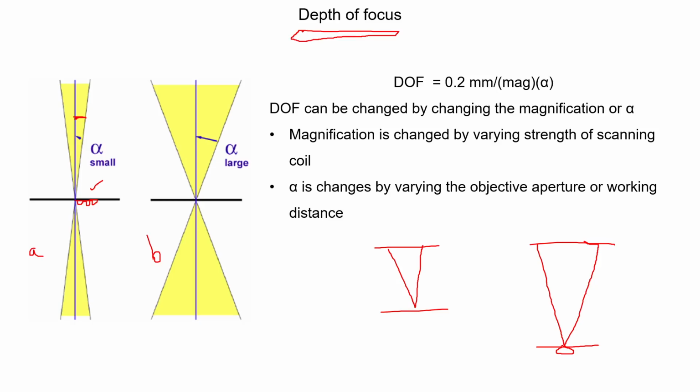I think, madam, there is an optimum distance at which we get the high spot size. I'm just discussing how working distance will affect the spot size, and the spot size will be related to this depth of focus. All these things are very intercorrelated.